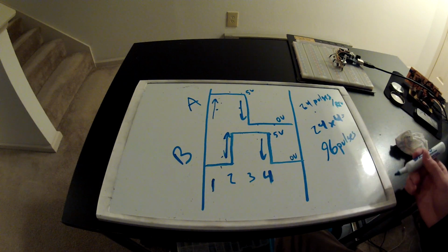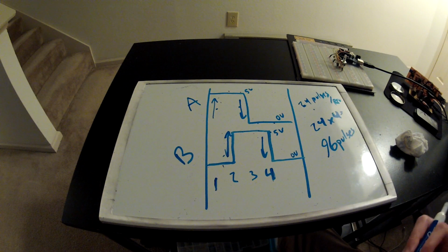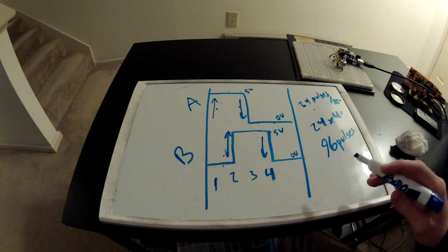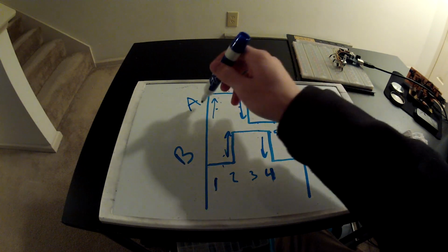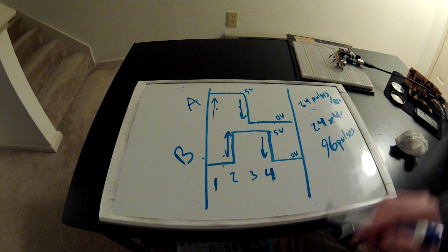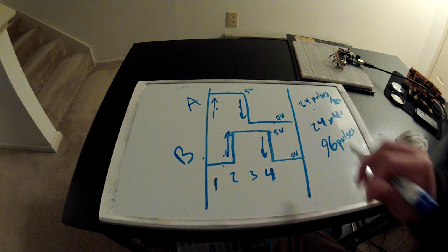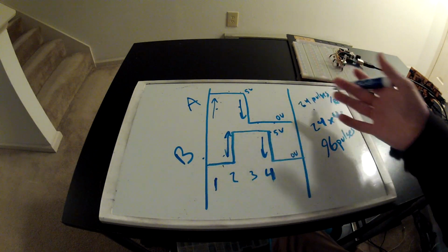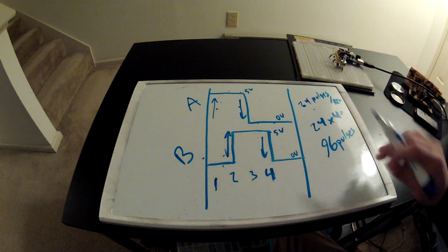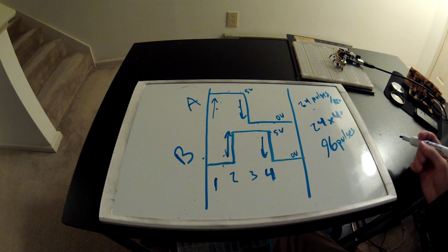Sometimes they call these encoders quadrature because of this. Okay, so anyway, that is basically how this whole thing works. We're going to wire up the A and B signals, as I showed in that circuit, into the interrupts of the Arduino, because you want to catch these very quickly. If you miss one, then you don't know, and you're going to lose your actual resolution. So let's shoot over now to the code.